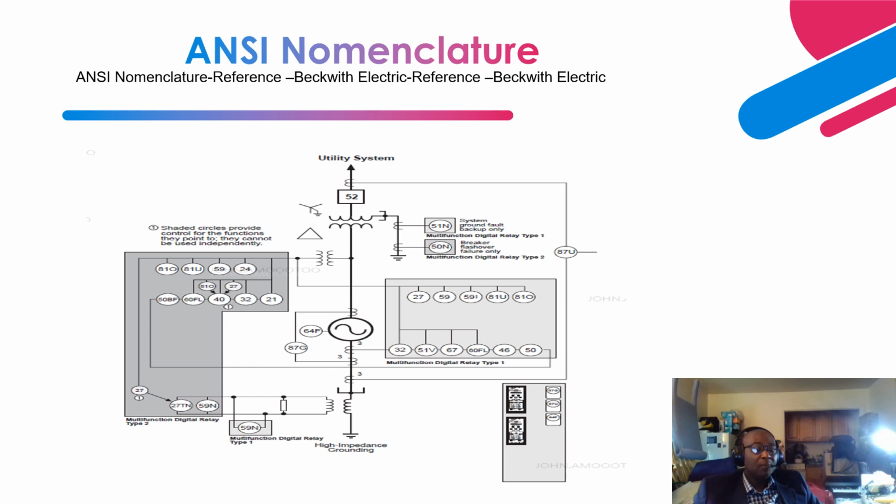24 is volts per hertz, and it's measuring voltage and dividing it by the frequency. Its goal is to prevent overexcitation of the generator and the generator step-up transformer, because overexcitation can cause saturation of the core of the generator and the transformer as well.